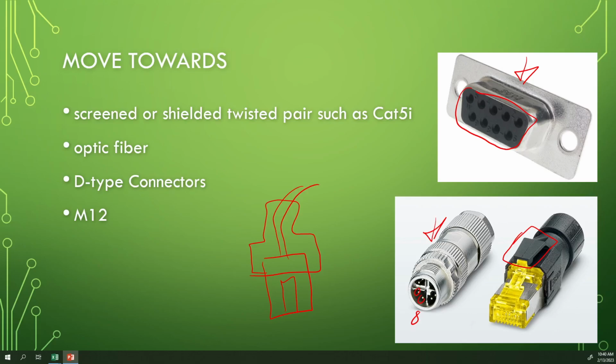I think so. It's all metal. It's a twist lock. You can see the threads going on here. They've probably got a waterproof gland on the end there. That's why you see more threads right here. So once you build your connector and you put it in, you screw that down, which cinches up on the sheathing on the outside to provide a nice waterproof, dustproof connection. Helps again with some flexibility and things like that. So it's a really great connection. I should go buy a few of these, but I'm sure they're also priced through the roof compared to our little plastic connectors that we just used the last few days. So there's always going to be that lovely give and take.